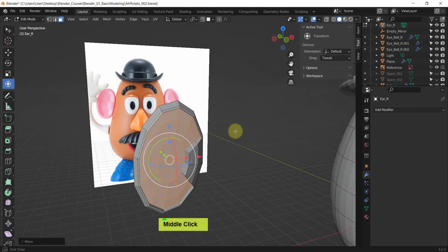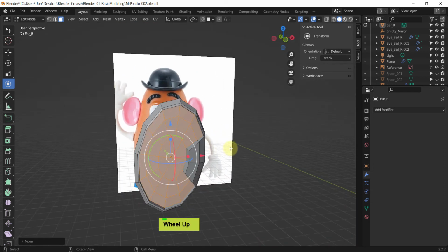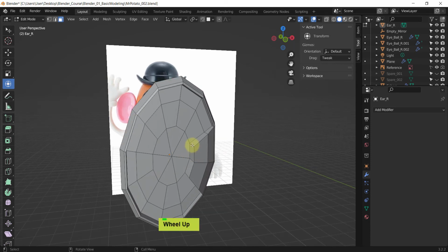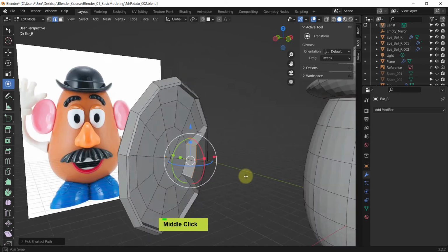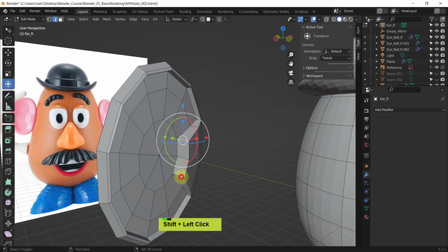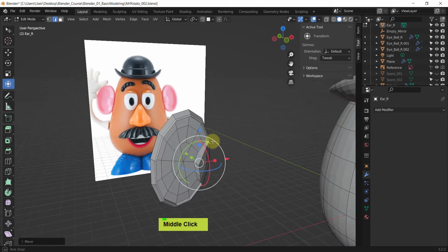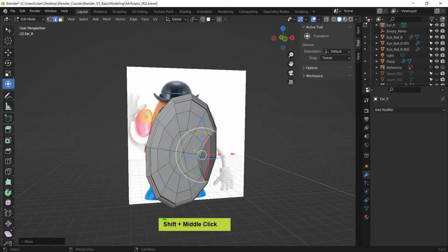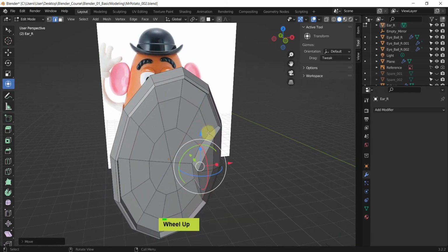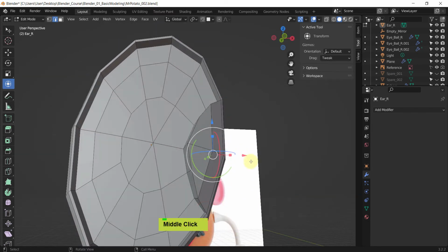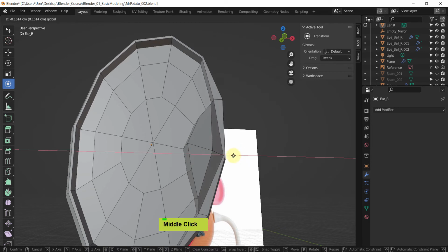And now it's time to take a look at the smooth version, but there's a little bit of an arc here. So to replicate that arc, I will select these 2 edges and this one and this one, and move them a little bit to create that nice circular shape. And here, because it's a little bit thicker, I will grab these edges and holding down Shift and grab and pull them a little bit in.